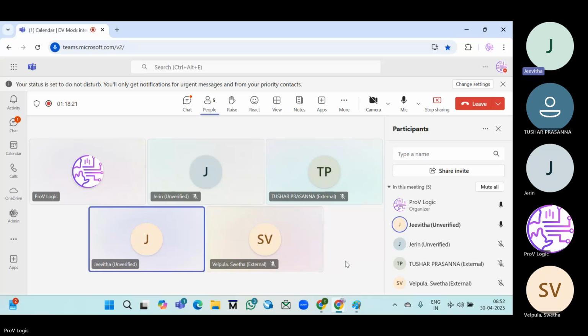$finish will terminate the simulation. $stop suspends the simulation. And $write doesn't go to the next line. If you want to go to the next line, we have to use \n.